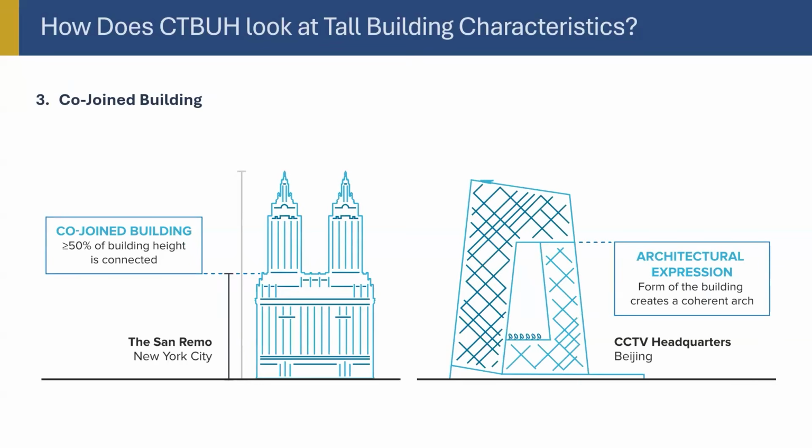Now, another one, which is a very important consideration that you will see later, is the buildings which are connected together by bridges. This is becoming so common. And you saw that video after the earthquake, 2 buildings in Bangkok, connected by a bridge, and they're separate. So how they did not design that bridge properly, and then the buildings moved, the bridge was disconnected, right? So bridges connecting the buildings are also another challenge. And these are co-joint buildings and so on.